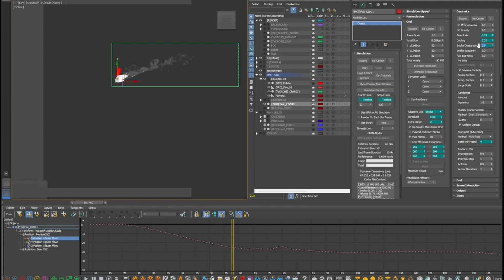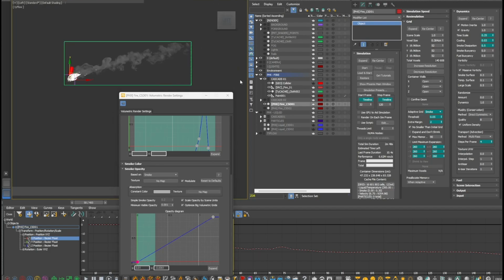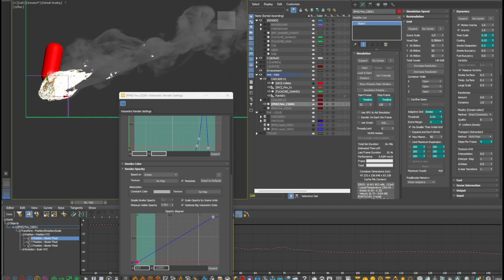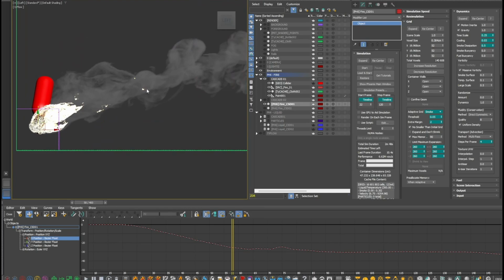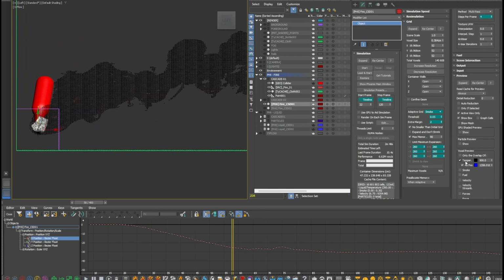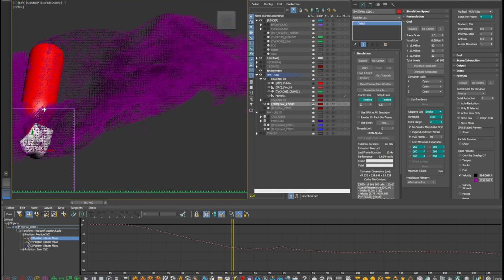But the smoke dissipation is increased to 0.5 since the smoke channel is what makes the grid expand, and I didn't need the long trail of lingering smoke making a huge simulator grid. The fluidity conservation method is left at the default, direct symmetric. Since this is a fast-moving object, I increased the steps per frame to 4. Having more substeps will increase the simulation time, but it will also smooth the velocities. This will produce smoother flames that are not chaotic and torn apart.